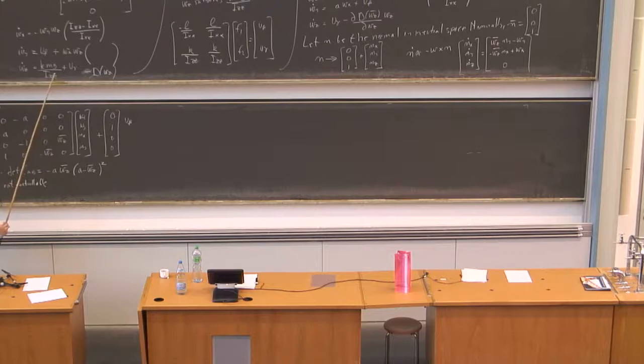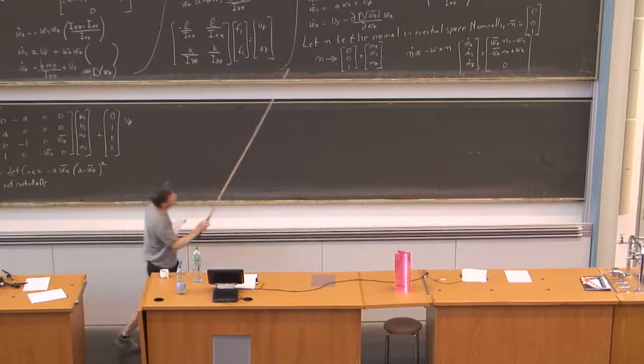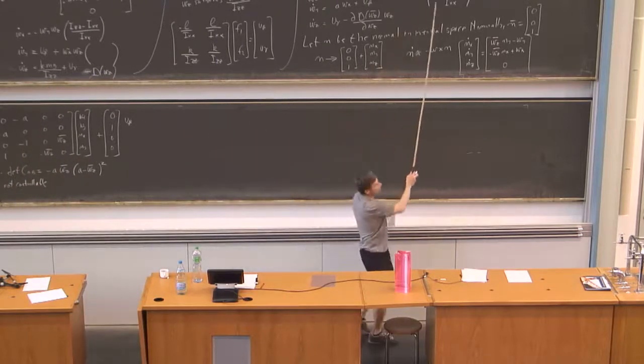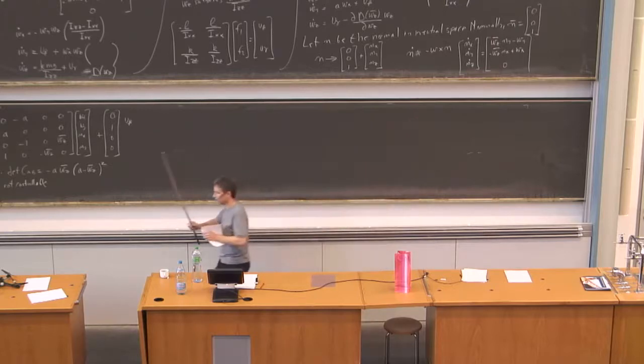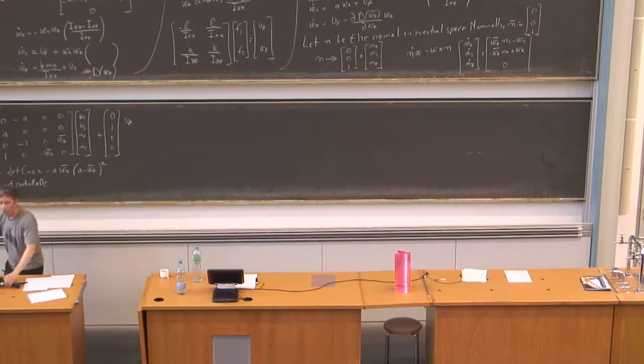Well, what is A? So we have this very nice result that basically tells us that if my mass moment of inertia about x is the same as my mass moment of inertia about z, I can't fly this thing. Not obvious at all. At least it's not obvious to me that that's the case. So this analysis immediately tells you that.